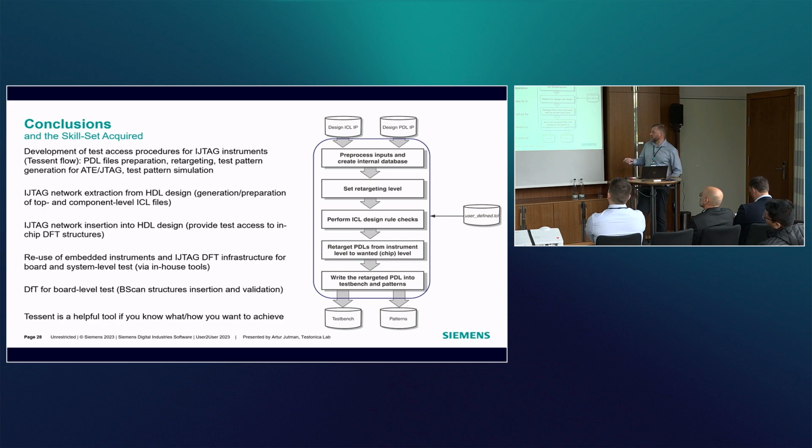Then you need to know how to perform IJTAG network insertion into the HDL design. In our experiments, we also needed to reuse embedded instrumentation from the chip, for board level testing or system level testing. All in all, Tessent was a very good tool to work with, when you know how to handle it, how it works, and what you need to achieve.